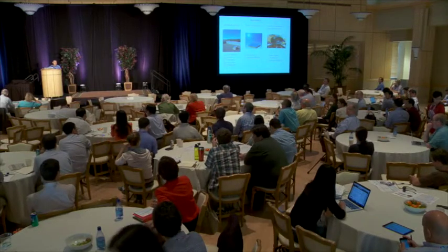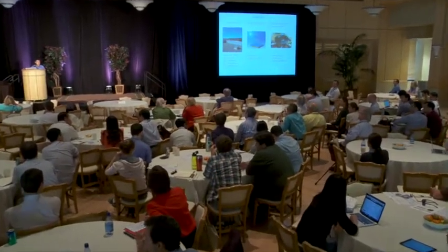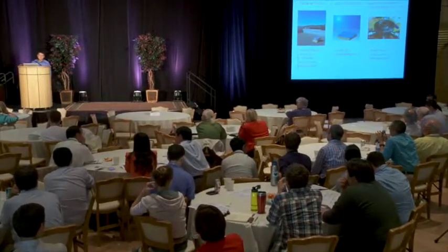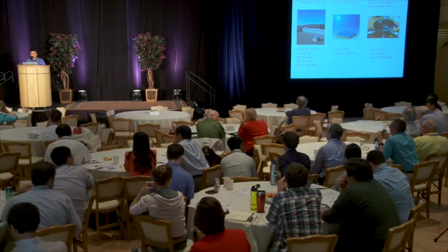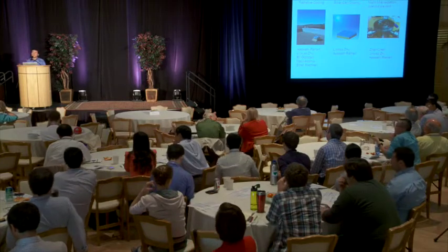Do you have to face the sky, or can you face anywhere which has thermal emission less than the ambient, or some material in the ambient that has less emission? You need to face something that has a temperature colder than the object that you are trying to cool. So the sky is the most natural one. And in fact, in many situations, if you have a low cloud, for example, the radiative cooling would be significantly affected because the temperature of that cloud is not very low.